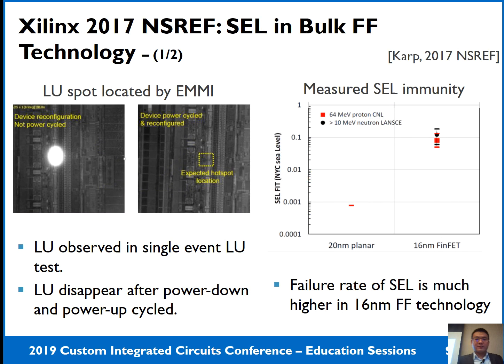A similar latch-up issue is also shown in this result from Xilinx, I think, on their real product, though it's a different latch-up test, a single event latch-up. But in their product, they indeed see the FinFET has the highest latch-up issue compared with the planar technology.